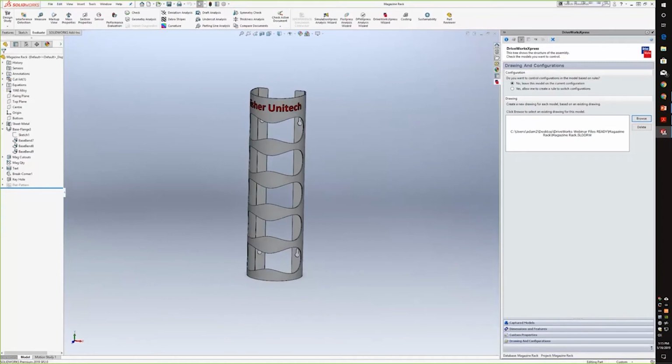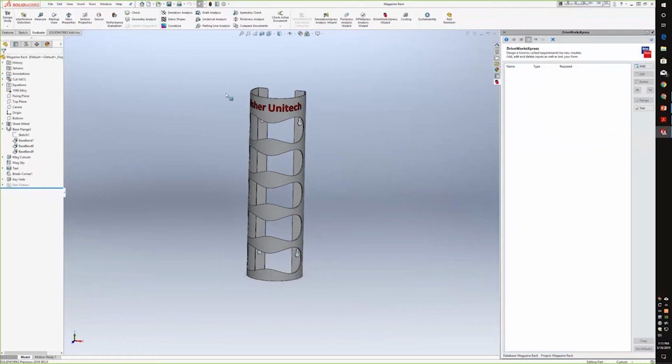All right, so from there, we pretty much have all of our capturing done. And much like a lot of things in SOLIDWORKS, you work left to right. So now that we're done with capture, we would move over to our form. And we'll start off by creating some text boxes here. So the first one I want to create is a text box for order number. So I'll go ahead here, type in order number.